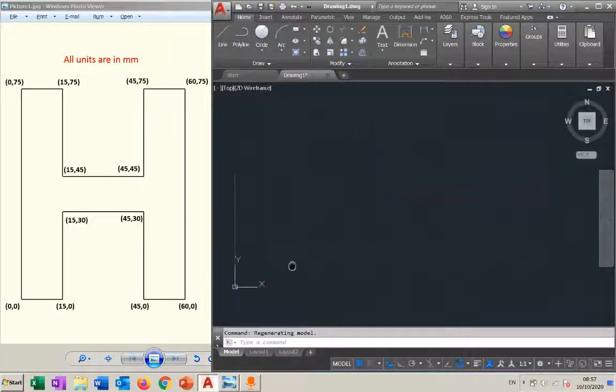Since we said that the screen is big, when I draw this one I might not see it. Now let me just test this one. Now I can start with line, so I can click on line. Line is activated. I can start with one of the points. Let's start with 0, 0, the origin, so I can type 0, 0.